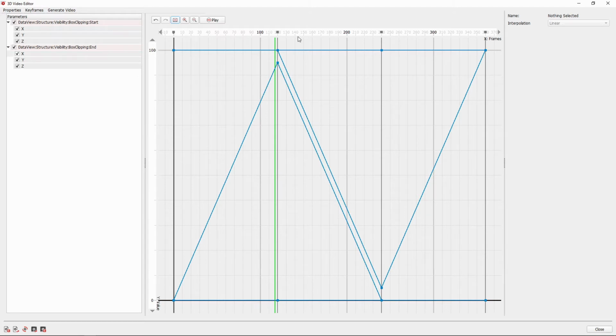Keyframes are groups in which the parameter control points are living in. Those are represented by a small blue box on the keyframe lines. A keyframe can be selected by left-clicking on the small dark gray box on the x-axis. By left-clicking and holding, we can change the position in time of the keyframe by moving the mouse left or right. To remove a keyframe, we can right-click the keyframe handle on the x-axis to call its options menu and